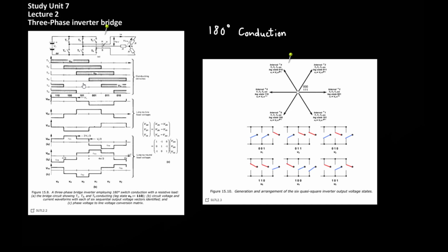Using this enumeration as a basis, a really useful diagram can be constructed which shows the switching sequence and what type of switching can be accomplished using this network. So shown here in the figure are the 6 switched states. There are more states, but these are the 6 useful states which allow for AC generation from a DC source.